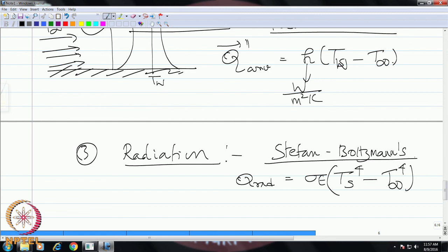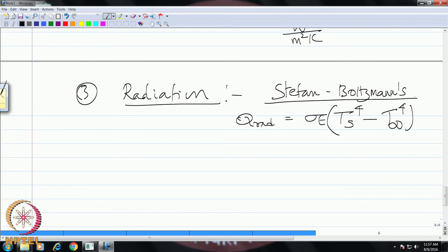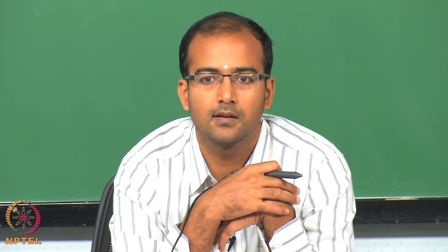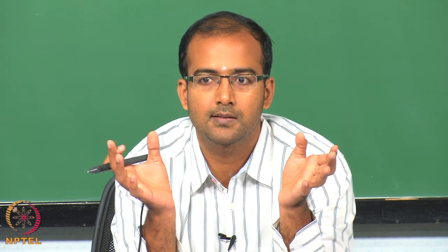For the black body, you have a distribution of the energy spectrum as a function of wavelength. So in radiation you have a spectral quantity, that means the energy or intensity is a function of wavelength, and it is also a directional quantity. In different directions of the sphere or hemisphere, the variation in radiation intensity is different. So it is a directional spectral quantity. Usually we average it over the directional, hemispherical space. We call this a total quantity, but still a spectral quantity.